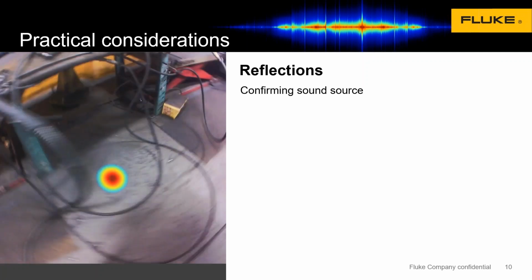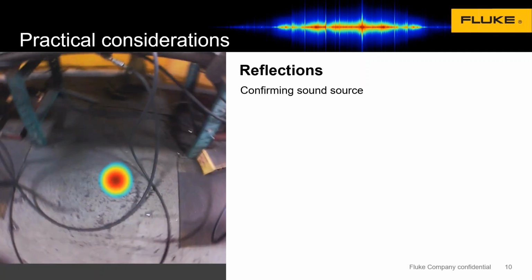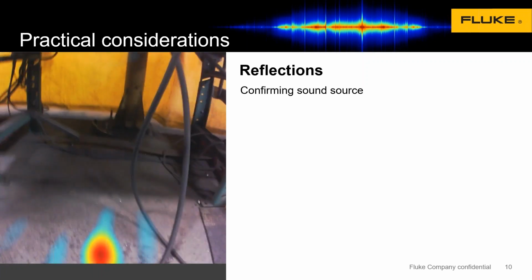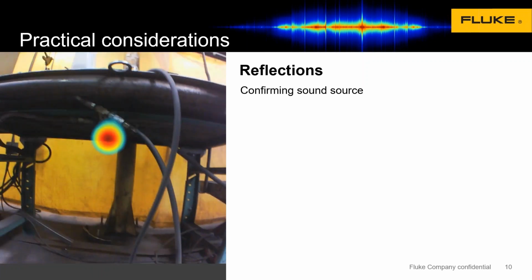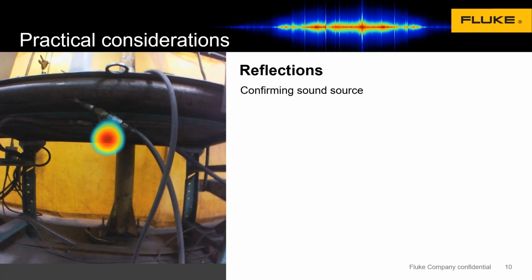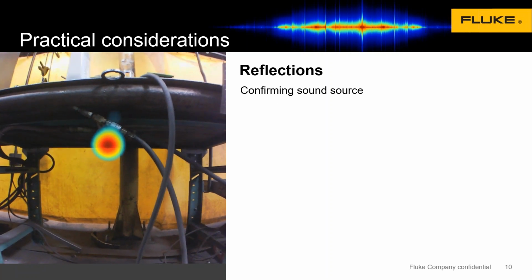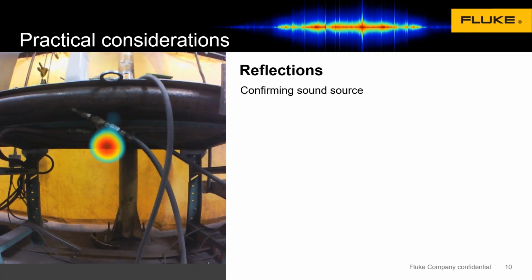Here's a video of the same thing. And we've done this again and again. So don't be afraid of reflections. If you see something that you're pretty sure is a reflection, you can use it as a clue to find out where the actual leak's coming from.